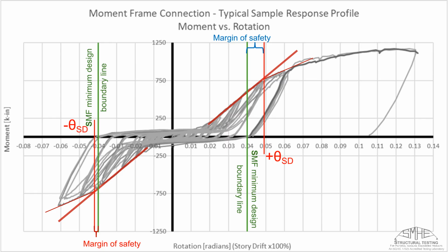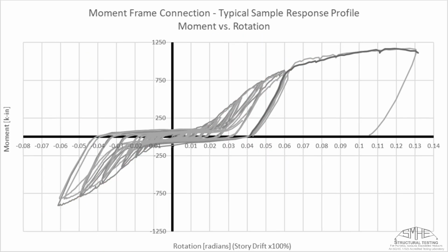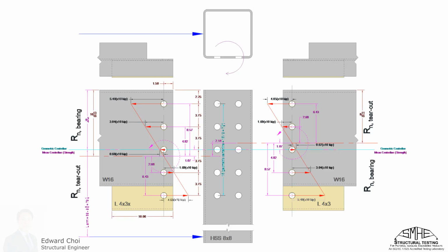frames. To wrap up, the area inside the hysteresis loop tells you how much energy is dissipated, while the shape and slope reveal your material's stiffness and deformation behavior. That's the fundamentals of reading hysteresis plots. The loop isn't just a curve, it's a story about your material's performance.